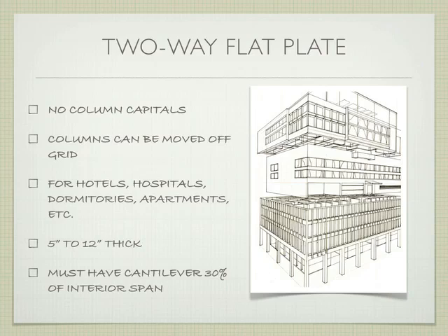So typically on this kind of a building, which is a very modernist type building, you're going to have this bit of an overhang on the outside, to compensate for the fact that it's a two-way flat slab system. Now, of course, architects love to do stuff like remove that.